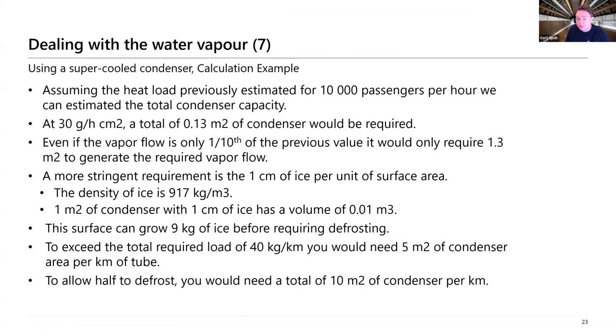So for 700 kilometers an hour, you would probably need to take significantly more water to overcome these drag figures. You can probably expect that you would have twice the propulsion losses and battery losses at these higher speeds. It would roughly be a similar trade-off if you go to a smaller tube and a higher blockage ratio.